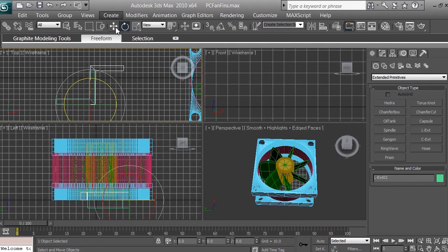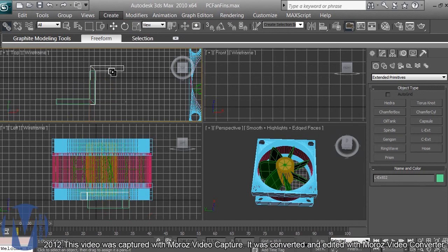What we're gonna do now, we're just going to link them like I did before. So we're going to use the link, select link item here, click on it. This guy is selected. We're gonna click on this guy again and then holding my left mouse button, go to this guy, click on it, and it's going to highlight for a few seconds, and now it's linked.